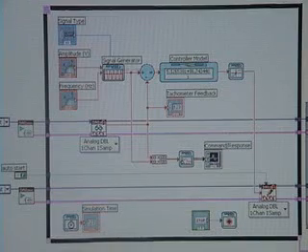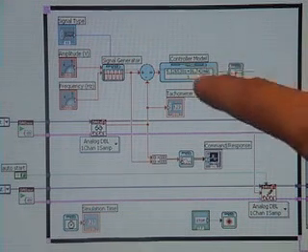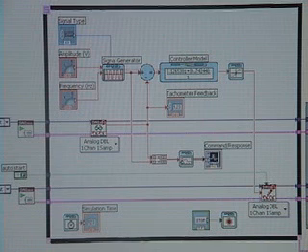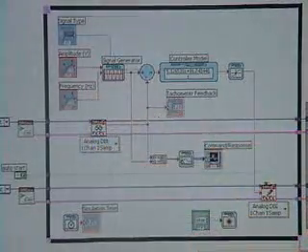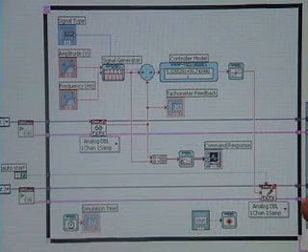Now the next step is to actually implement the control through hardware. So you'll see I essentially have the same diagram. I still have my controller model shown here, but you'll see I no longer have a plant model. In essence, the model or the transfer function I was using before is now going to be replaced with the actual DC motor. So in this case I have an input signal coming in here, so I'll read what the DC motor is doing. I'll send it through my control loop, and then I'll output the correct voltage to keep it at the speed that I want.